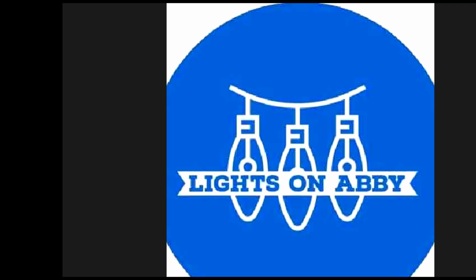Some people, me being one of them, I have some singing trees and they're 350 pixels and they're running fine with a reduced brightness of 30%. I take it down to 30% and I can run it without power injection. So that's the setting that you have in xLights where you can globally set your brightness. It's in your controller configuration, or you can even set it at the prop level. So depending on your brightness, depends on how many amps it draws.